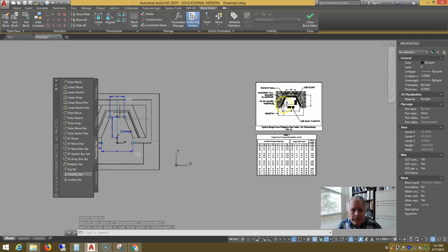I'm going to draw the outline in here and then use the offset command and the trim, extend, and mirror commands to get the rest of this. So polyline from 0,0, turn ortho on, up 4, at 6.5, 16, 11, at 6.5, negative 16, back down 4. Offset 4, and these are nominal dimensions for brick, not actual dimensions.